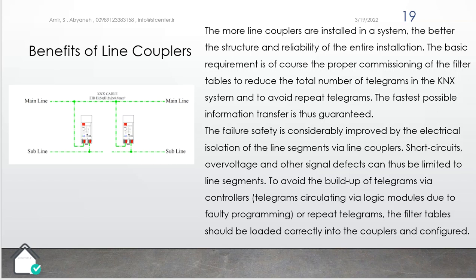Okay, the benefit of line coupler. To my experience, if you use more line couplers, it is much better. Okay, the drawback is it makes your project a bit expensive because you should pay more for the line couplers plus power supplies, or you should pay more for the IP router. Okay, but we have many benefits from it. Let's go and see what the book provides for us.